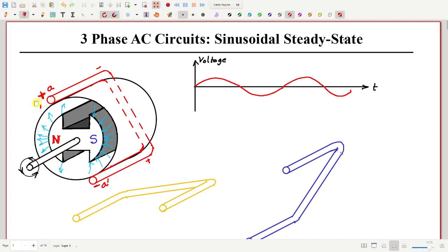So the conductor is moving in this direction. Your forefinger should point along the flux. Basically the conductor is moving along the periphery of the cylinder, and in the radial direction we have the magnetic field flux lines, called B. This is velocity V. Then perpendicular to that, along the height or length of the cylinder, we will have the EMF. And if you apply the right hand rule, you will get the direction of EMF like this.